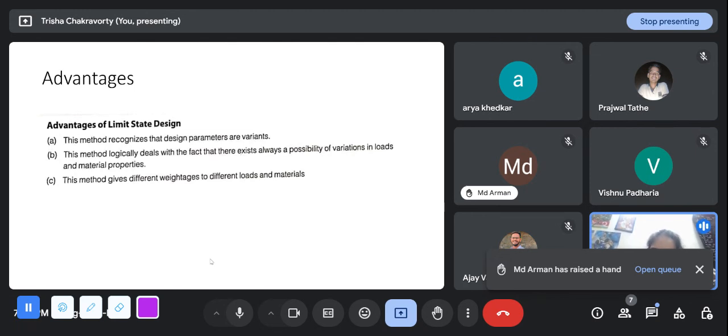So in my design I will only allow the stress to develop up to 235, so that even if that section was weaker, like, we know that in an ideal case the section will have yield strength of 250, but we don't allow the stress in it to develop more than 235. 235 is just a representative value I'm using. 235 is basically the 250 divided by the safety factor.